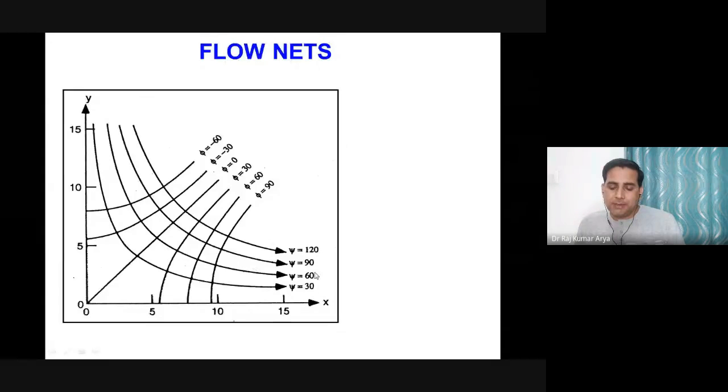Now here psi equal to 130 means you are moving close to a particular surface, or if it is the end of the flow, it means that surface is also moving with this particular velocity, because from this side that velocity can be calculated. Now, what happens in between? Here the gap between the streamlines has increased sufficiently.